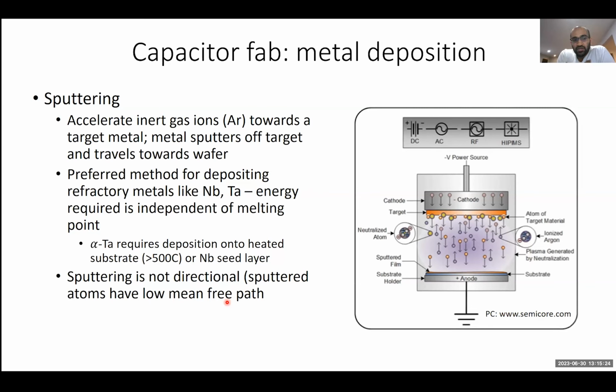Whereas we use our sputter to deposit niobium and tantalum. And because we do these high temperature processes, we really don't want to deposit aluminum in a chamber that we're heating up to above 500 degrees. So we generally like to keep those processes separate. But I think I have heard of other groups that do sputter aluminum. The question about which is better when it comes to aluminum, I'm really not sure. I don't know if there's been a systematic study that has looked at that.